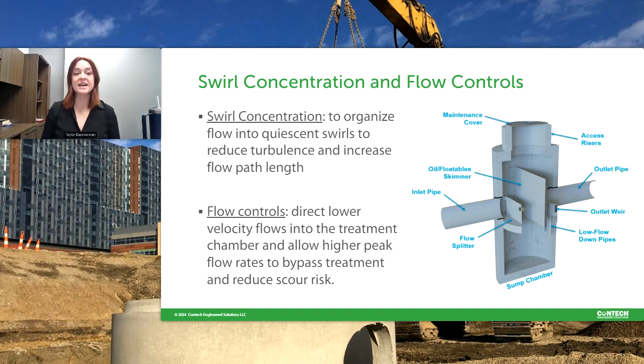Yeah, thank you, Marco. So, like Marco said about different sediments and different HDS units, not all of them are the same. And that definitely comes into factor because not all of them look the same. They all come in different shapes and sizes, from a manhole to vault configurations. These treatment units can use a variety of different internal controls to promote gravity separation and prevent the resuspension of